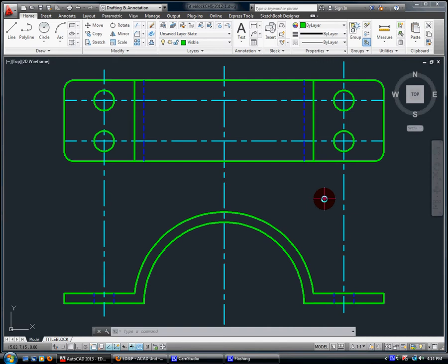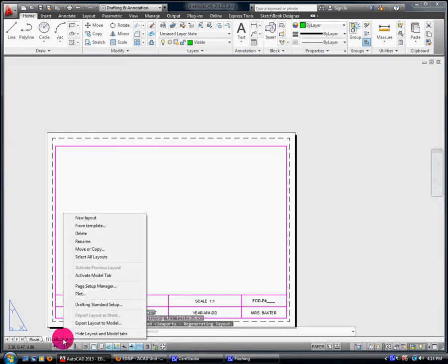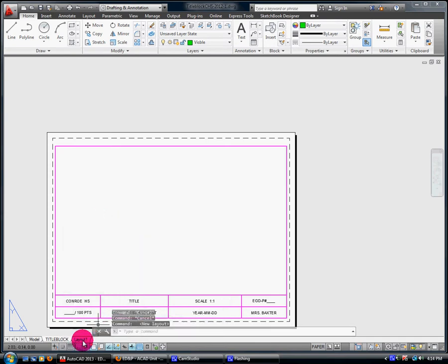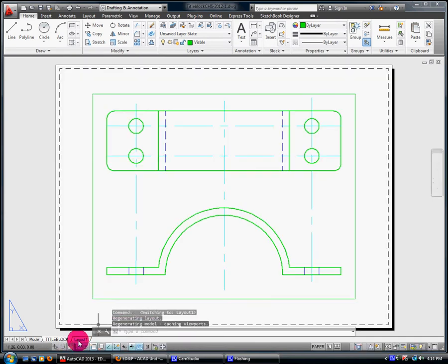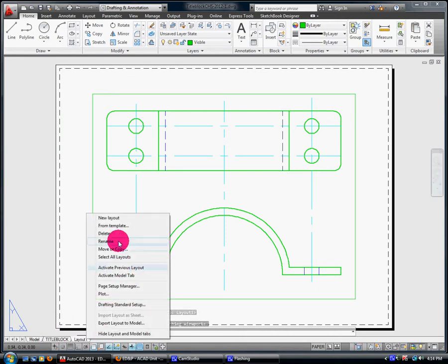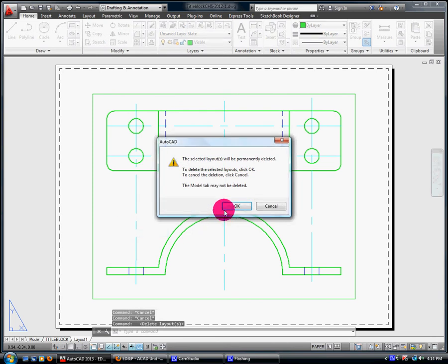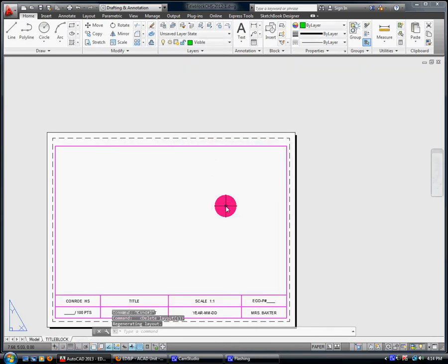If I needed to do a detail that showed just this corner here, I could. I don't need to right now, but I could simply have another tab here: right click, add a new layout, make a new one, and keep going. I could use multiple, so I could have different pages for every single thing that I need. You can have, if I remember correctly, as many as 20. So if I had a really detailed drawing, I could really detail it out this way. But for right now, we're just going to do a basic one.